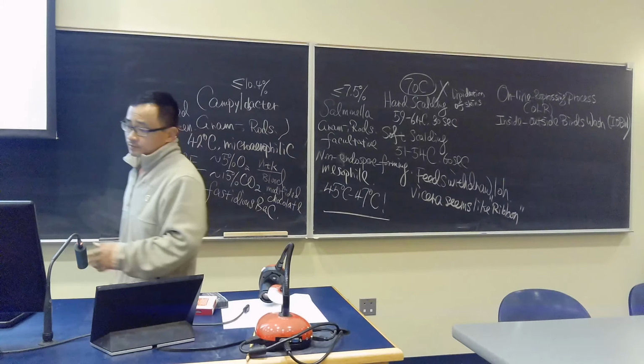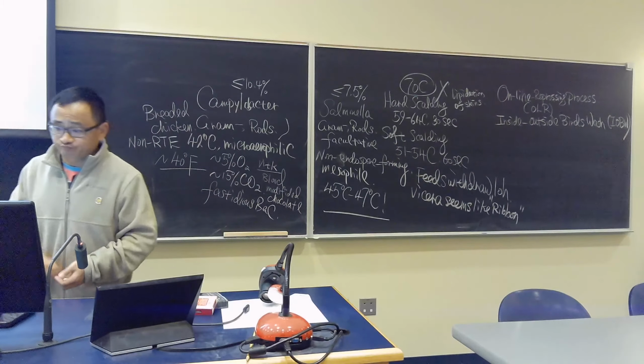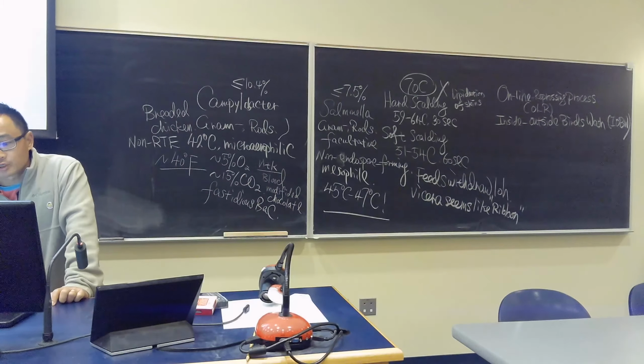Number one, the pressure. The nozzle has to work very well. It needs a good distance, the pressure, and it has to cover the big surface. So you can see the nozzle here looks good. Here not looking good. Some of the distance coverage is not enough pressure. Look at here, this doesn't even work. So you need a certain distance, pressure, and covered area.